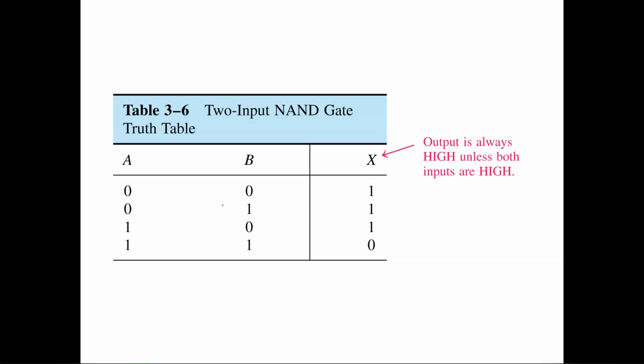So does this table make a little more sense to y'all? That table, I can easily understand it that way. The other way, where you have to draw, I get confused. So this is the best way I can show you how this works: anytime you have a low signal to no signal, this guy stays on. Whenever you get a high signal on both ends of it, that's whenever it'll turn off. Does it make sense to everybody?